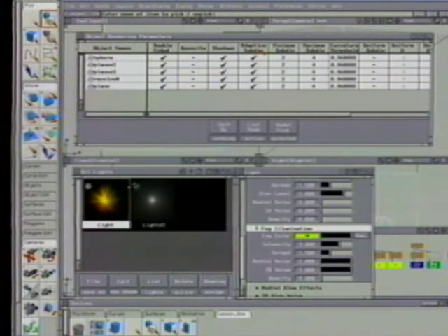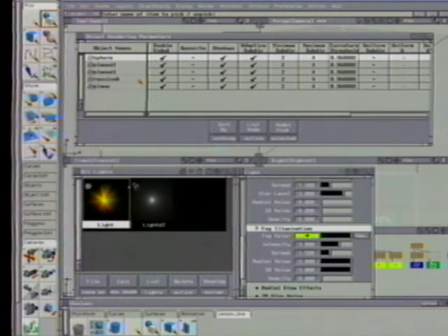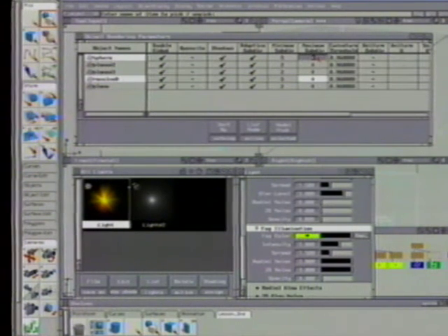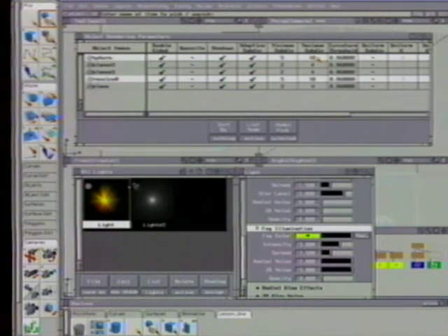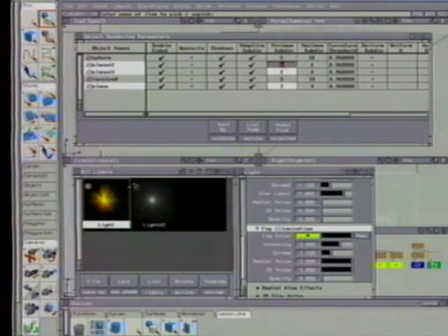Now go to the Windows menu and choose Render Stats. In this window, you can see the render stats for the objects. The default setting is 2 to 4 subdivisions per isoparm patch. You will need higher settings for some of these surfaces. Set 5 to 10 for the sphere and the revolve since they are more complex shapes. Note how by shift selecting both objects from the list, you can change their values at the same time.